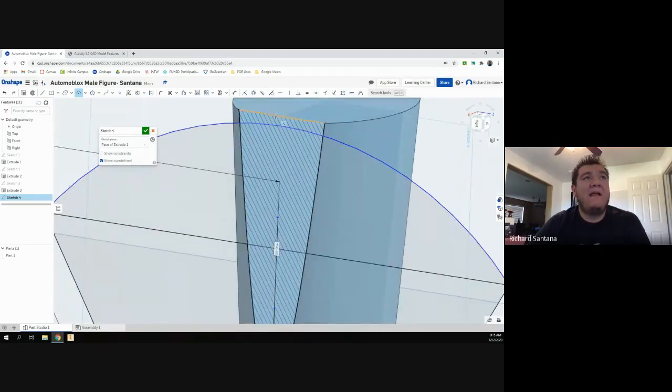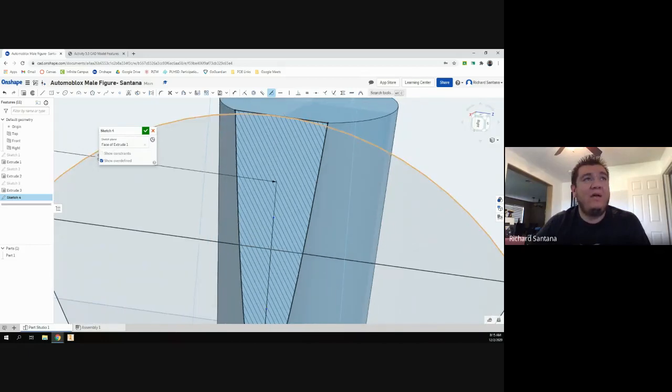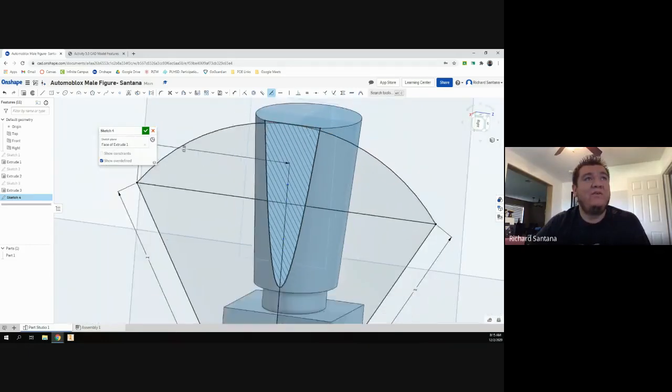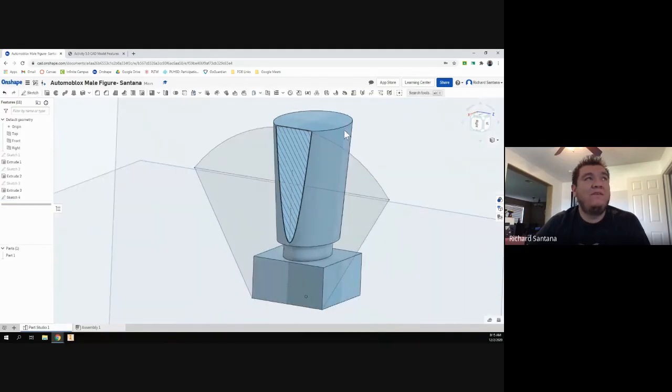All right, it doesn't automatically latch onto the edge here. What you need to do for that is click on this tool right here, the tangent tool. So you click on the arc, and you click on this line, and you'll see that it automatically closed that gap and made sure that the arc touches that edge. Once we've done that, we can go ahead and finish our sketch.